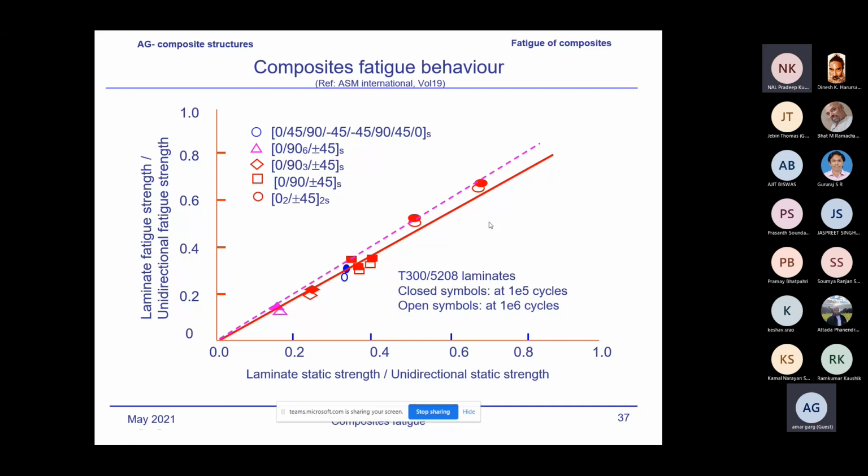But in industry, thickness will be maintained. Whether 0 degree or a laminate of a different stacking sequence, thickness will remain the same. In fact, it may not depend significantly on thickness unless the coupon buckles. So you make the coupon so that it doesn't buckle when you are cycling it. Some thickness like 3 millimeter, 4 millimeter coupons you might use.